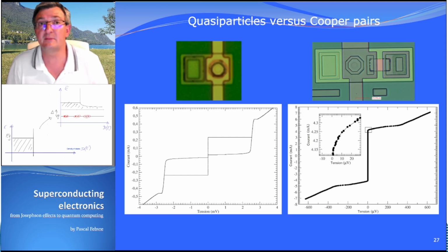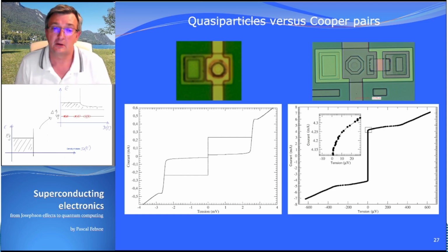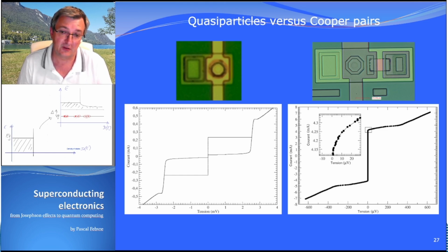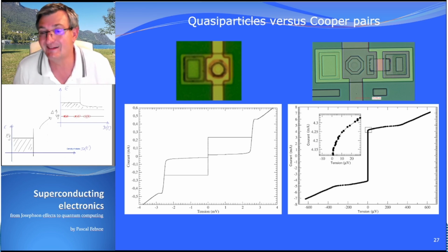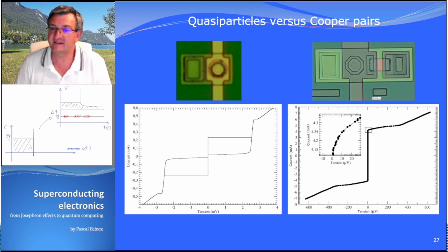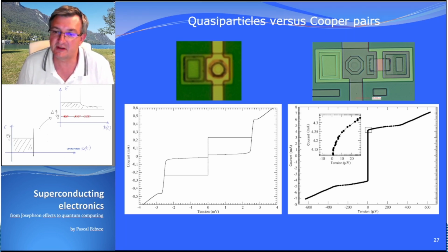So you can do frequency mixing, and it's very interesting for receivers, for microwave receivers, to convert a signal from a high frequency to a lower frequency. It's used, for example, historically for radio astronomy, where you can use these devices to measure signals in the sub-millimeter band or terahertz band, and convert them to lower frequencies by mixing the signal that you want to detect with a signal applied on board, which we call a local oscillator signal.